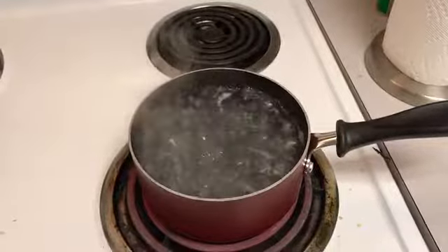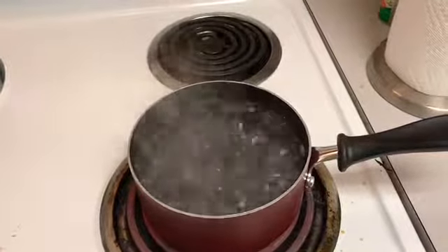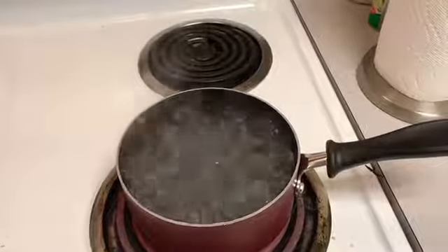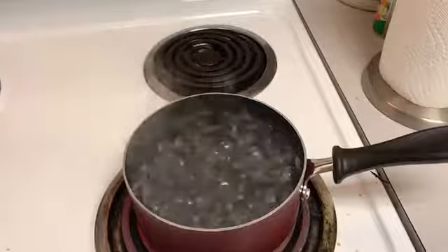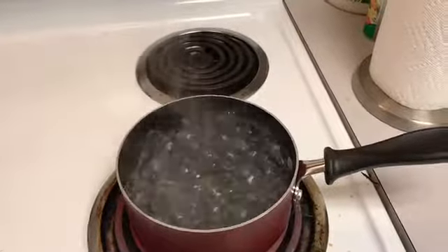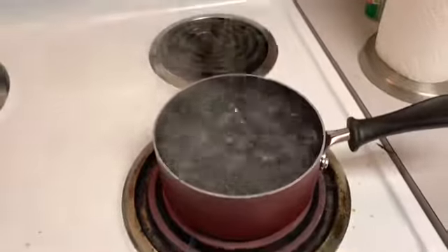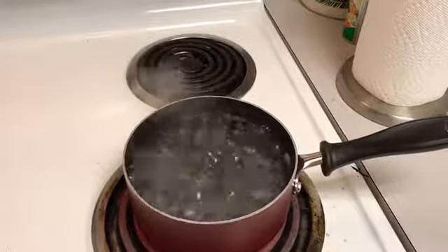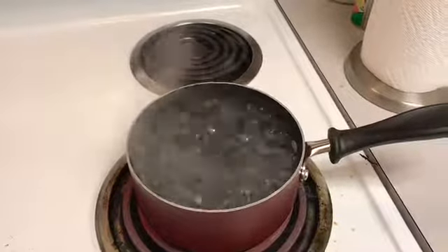After nucleate boiling, we have transition boiling, which occurs between 30 degrees Celsius excess temperature and 120 degrees Celsius of excess temperature. A fraction of the surface is covered by vapor film, and h will decrease with increasing temperature excess. Finally, we have film boiling, which occurs at temperature excess greater than 120 degrees Celsius. The heat transfer by conduction and radiation occurs across the vapor film.